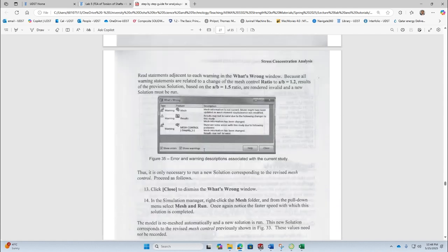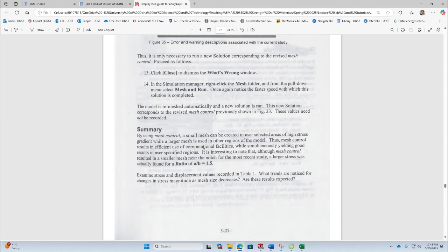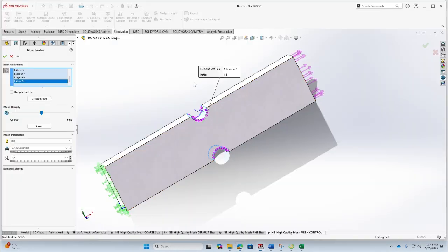So he's doing it 2 times basically with different mesh ratios. Let me go back. It is mentioned coarse size. Yeah, he started with the coarse size, but you need to specify what will be the density on this one, default or fine. So we can go for either default or the fine, or put it anywhere in between that we want. But I'll just keep it right now for the default one.